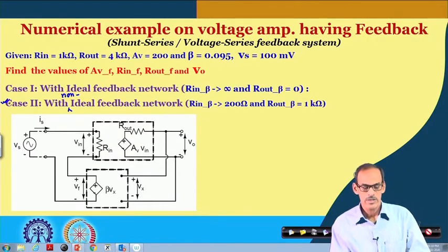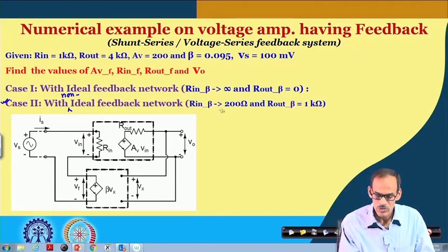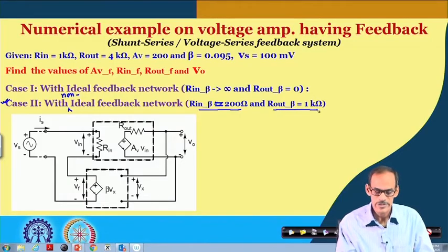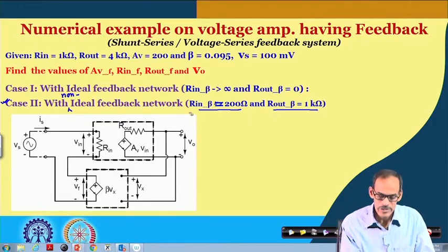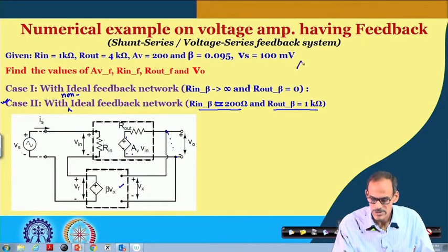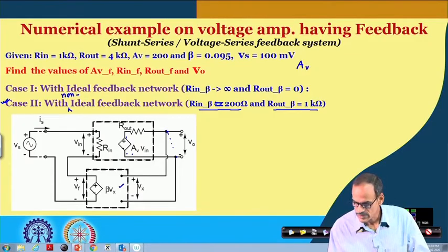Before we start, since we do have finite input resistance and output resistance of the feedback network, the input resistance here is affecting the output port. So, the voltage you will be getting here is not the same as this internal voltage, rather we may say that it is the load affected voltage. Let me use a different color here.